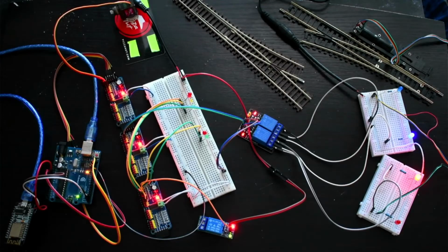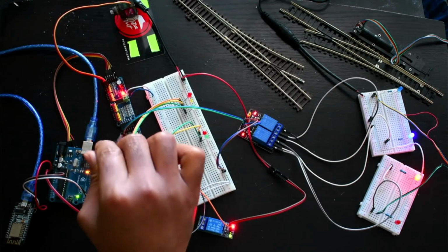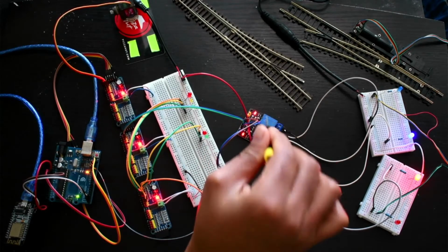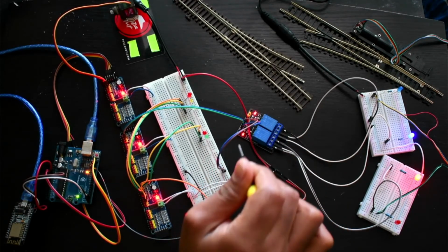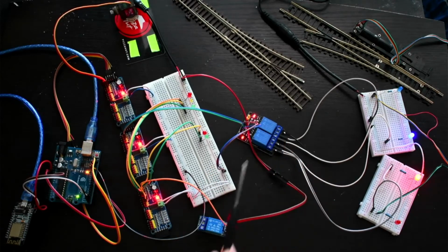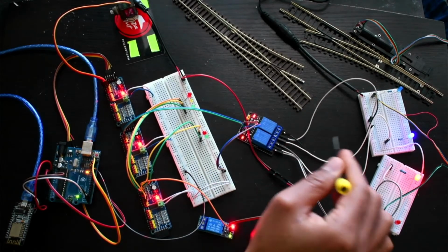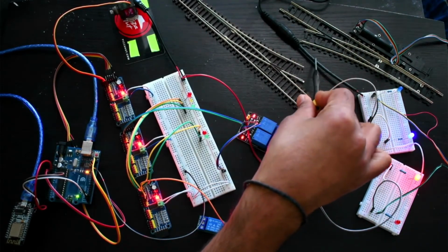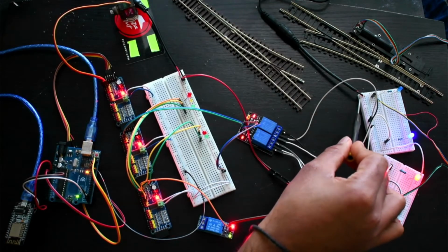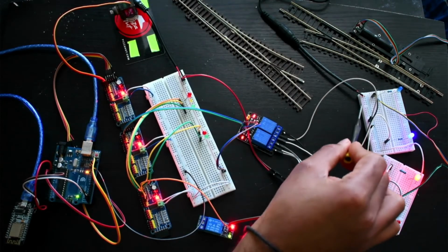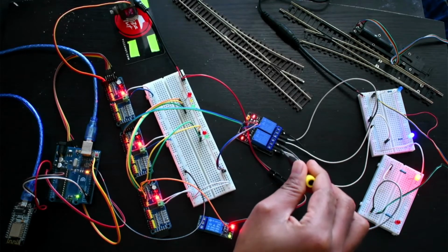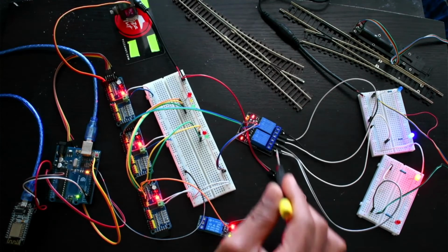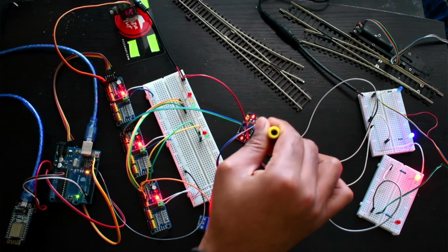Here you can see, from board number 1, pins 0 and 1 go to the relay switches to control the throw and close positions, and this relay switch is powered by 5 volts and GND, taken from this breadboard here. To control the snap turnout you need an external 12-volt power supply. This is coming here, and from this breadboard the 12 volts goes to this middle pin, which is the common, so that both the throw and close positions through both relay switches will be active.